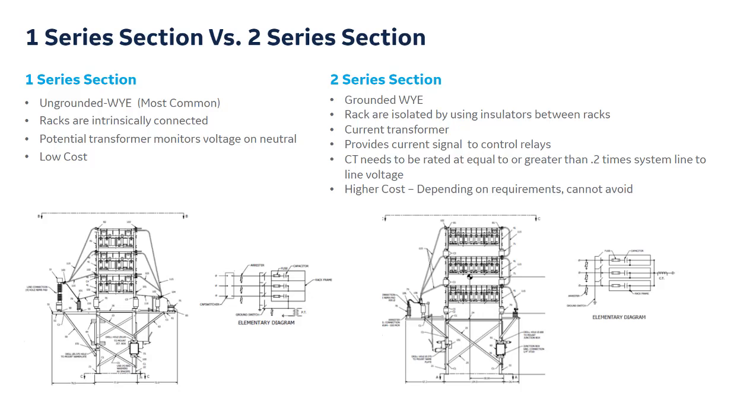The simplest method to detect unbalance in single ungrounded Y banks is to measure that bank's neutral or zero sequence voltage. If the capacitor bank is balanced and the system balance equals 0, the neutral voltage will ideally be 0 as well. A change in a phase of the bank will result in a change in the neutral or zero sequence voltage, which, like I was saying before, will drive a relay for an alarm or a breaker close.